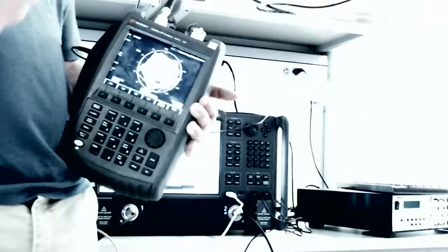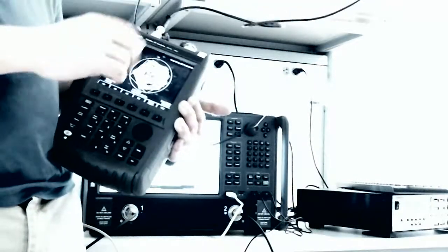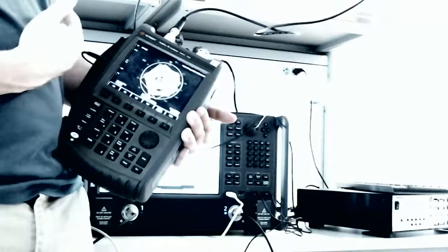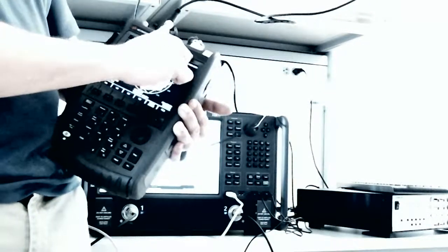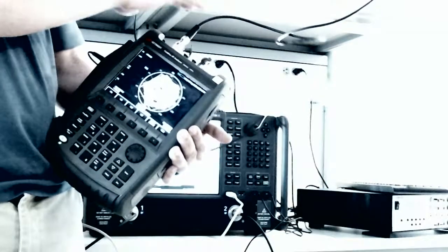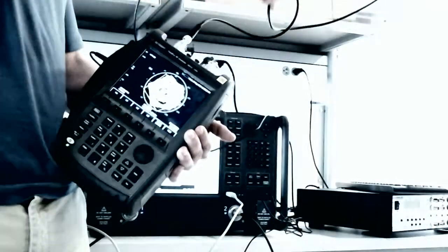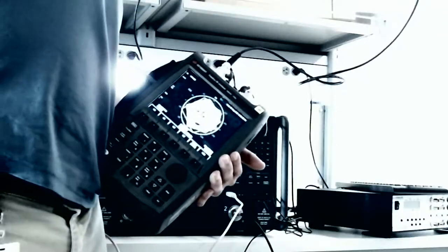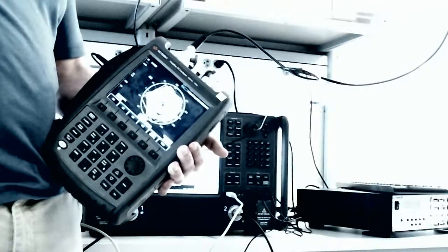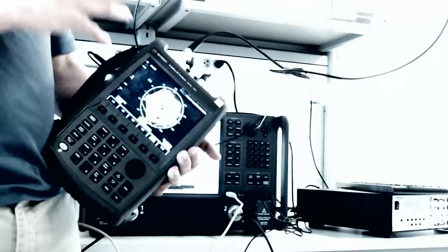So if I'm trying to do an impedance match and I'm using a BNC cable, maybe I can get away with it, because right now I'm doing that full sweep from megahertz to 4 gigs. But this is not even the 13.5 that we were looking at here. So if you're trying to do this with BNC, you can really forget about it, because depending on how you position this, and obviously with an antenna, depending on what's close to it, it's going to be entirely different. So this is why you really want to make sure you get good VNA cables for the measurement.